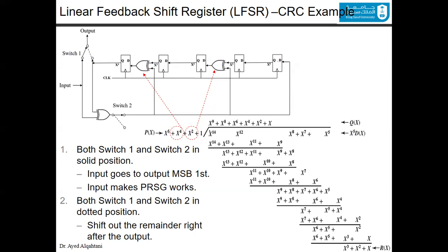You can calculate it if you have a polynomial, and let's say that you have this message that you want to check its CRC. The message originally was a bunch of zeros and ones. You shift them to the left by 5 to give a space for the result of the CRC, the value that will be stored in the flip-flop after you do the CRC calculation. And this division is actually not the one that you maybe studied in elementary school. It's using exclusive OR.